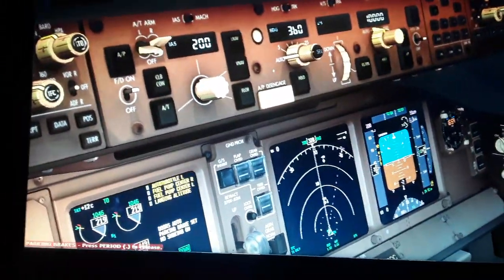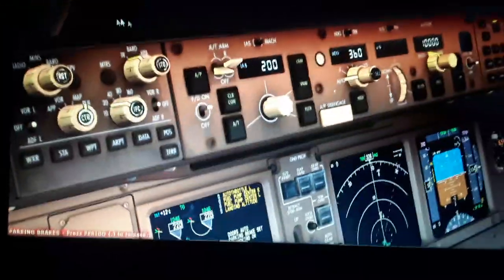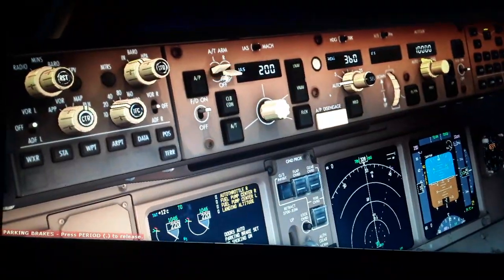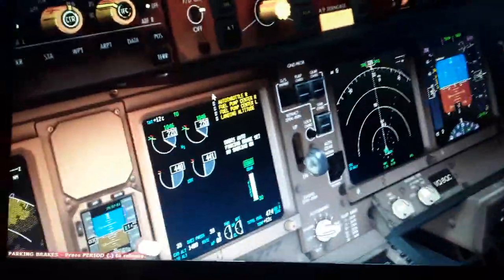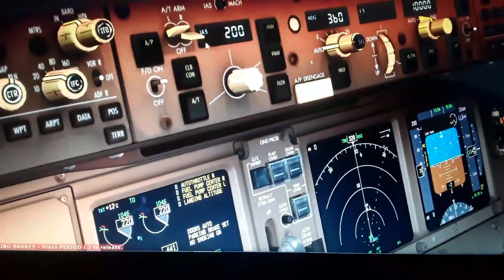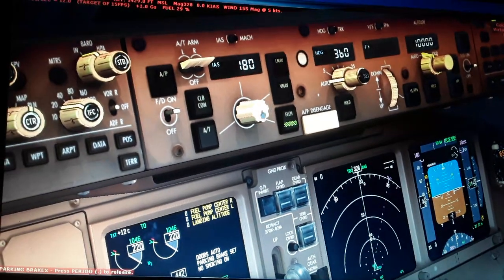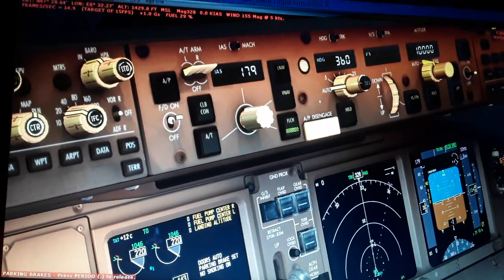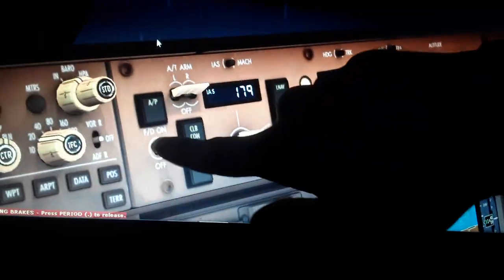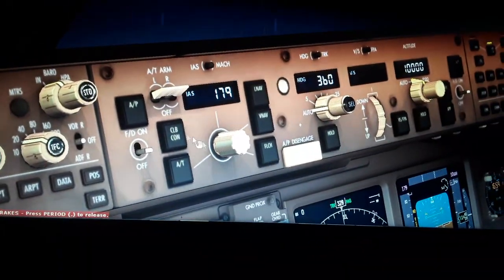So we can set here autothrottle left off. You will see autothrottle left off, autothrottle right off, both off, one the right off. You will see the autothrottle right display with yellow warning over here. Both on. Flight level change, here you can change the mode, turn off the flight director like this.